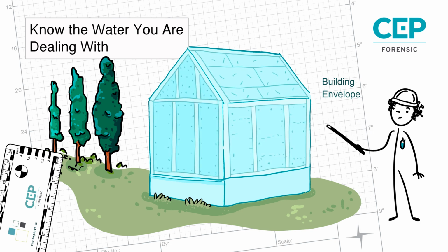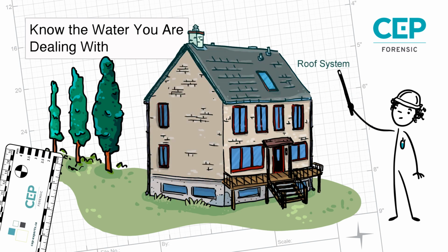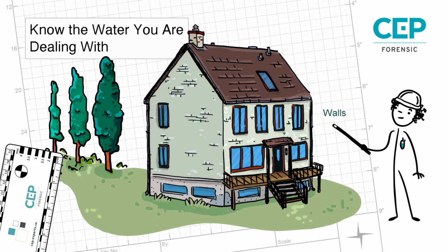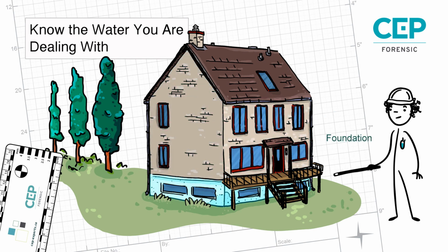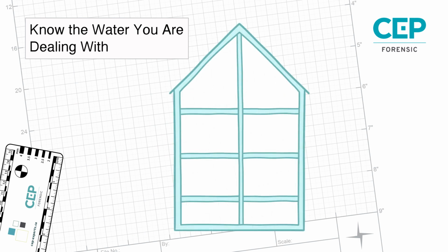These components generally include the insulation, air barrier, vapor retarder, and various flashings. In addition to these components, a roof membrane or shingles and roof decking are unique to roof assemblies, while exterior cladding, wall sheeting, and windows and doors are unique to exterior walls. Foundations include either damp-proofing or waterproofing, which act as the envelope component applied over the structure. Water losses due to building envelope failures can present themselves in many forms.